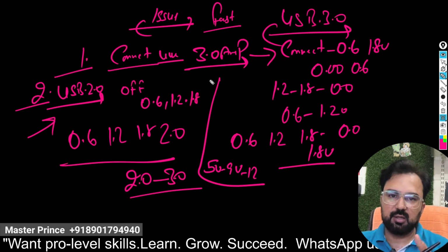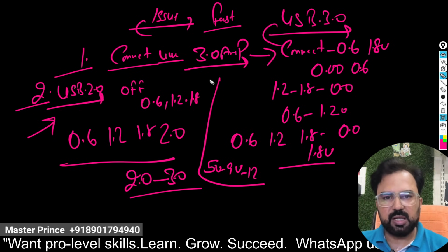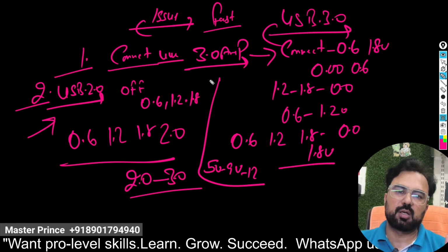Maybe the IC is faulty, maybe any line does not work, or the circuit is open, or any line is shorted, or the communication is broken. So the fast charging circuit does not work, and it comes back to disconnected. The CPU thinks there is an error, so it disconnects, but again it starts from 0 because the charger is connected.